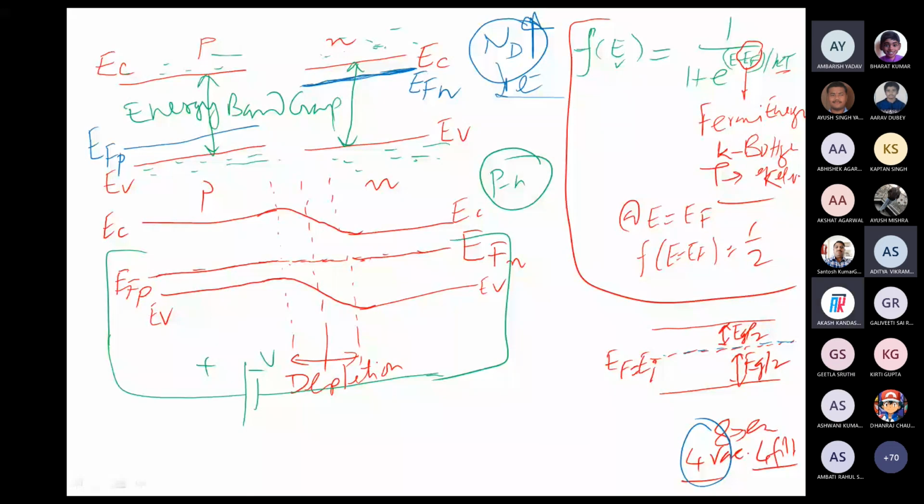And as already qualitatively we have discussed, this is a forward bias voltage. Okay, so forward bias voltage will tend to reduce the potential barrier. So actually the potential barrier reduces something like this here. Okay, so potential barrier remains this here as opposed to the earlier value of this thing.